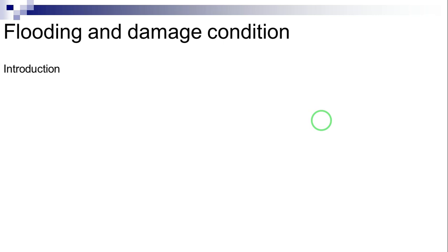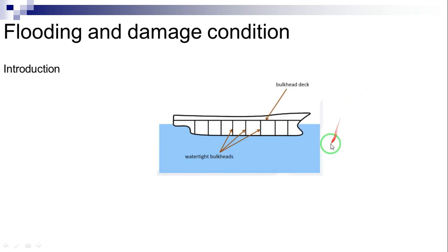To achieve survivability as defined above, the ship hull is usually subdivided into a number of watertight compartments. The length of the compartments should be such that after the flooding of a certain number of adjacent compartments, the waterline shall not lie above a line prescribed by relevant regulations. The same regulations specify the number of adjacent compartments that should be assumed flooded. This number depends on the size and the mission of the ship. The reason for considering adjacent compartments is simple.